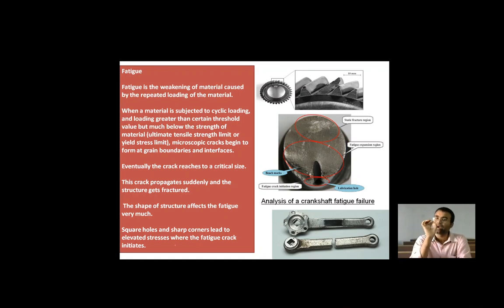एक बाल के बराबर, बाल की पतली थिकनेस के बराबर एक हल्का सा क्रैक होता है ड्यू टू साइक्लिक लोडिंग, और चूंकि वो स्ट्रेस कंसंट्रेशन होता जाता है उस बाल की जगह पे, मतलब हेयर क्रैक की जगह पे, तो वो बढ़ते बढ़ते उस पर्टिकुलर मटेरियल को ब्रेक करने का काम करता है. So eventually the crack reaches a critical size, this crack propagates suddenly and the structure fractures. आपको पता भी नहीं चलेगा और सडनली वो चीजें हैपन हो जाएंगी, और ये बहुत ही कॉमन सा प्रॉब्लम है किसी भी स्ट्रक्चर में.